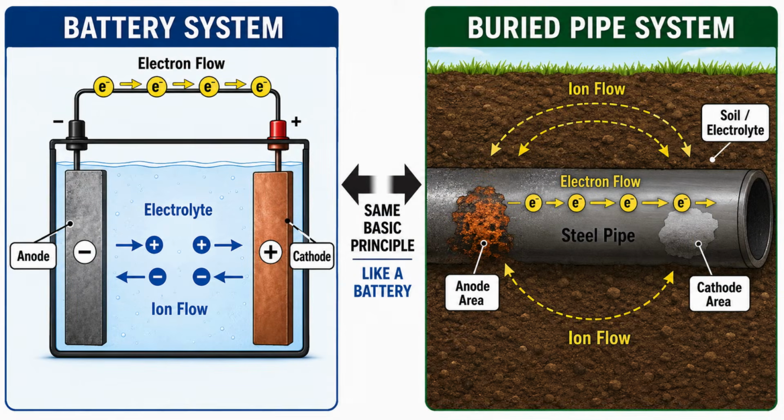A helpful way to understand cathodic protection is to think about a battery. In corrosion, the steel and its environment can form small natural corrosion cells. These cells create anodic and cathodic areas. Cathodic protection interrupts this natural corrosion behavior by adding another source of current. We connect the steel structure to another material or to a DC power source. Then the protective current flows through the soil or water to the steel. The steel receives current and becomes cathodic. That is the basic principle.